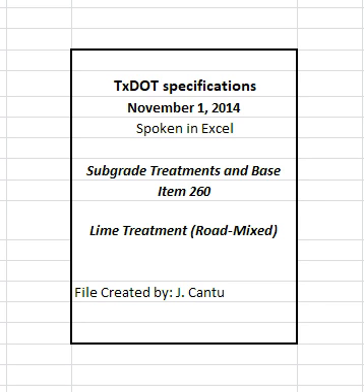5.1.1 Hydrated lime. 5.1.1.1 Dry. Lime will be measured by the ton, dry weight. 5.1.1.2 Slurry. Lime slurry will be measured by the ton, dry weight, of the hydrated lime used to prepare the slurry at the job site. 5.1.2 Commercial lime slurry. Lime slurry will be measured by the ton, dry weight, as calculated from the minimum % dry solids content of the slurry, multiplied by the weight of the slurry in tons delivered.